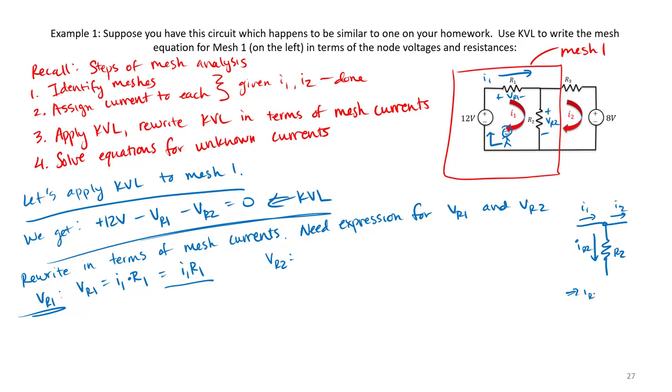Here we can determine by Kirchhoff's current law that plus I1 minus I2 minus IR2 equals 0, so IR2 is just I1 minus I2. So by that reasoning, the voltage drop across resistor R2 would be equal to R2 times I1 minus I2. That's the resistance times the net current flowing through that resistor.